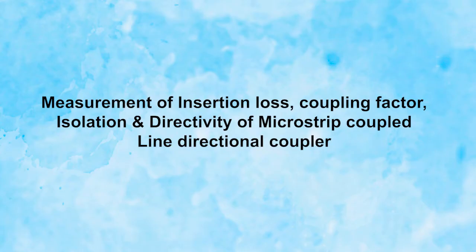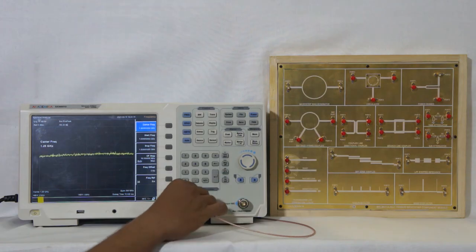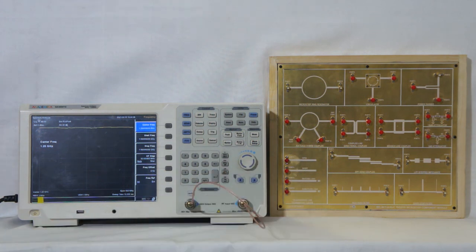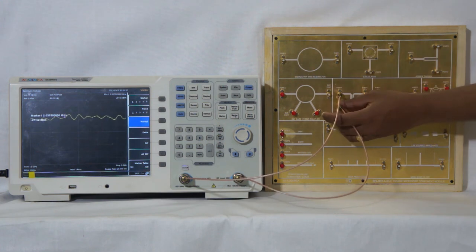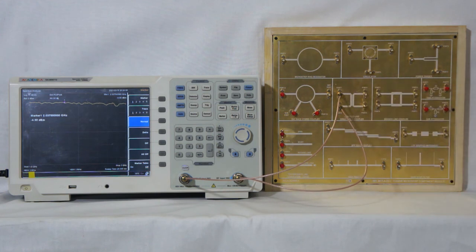Measurement of coupling factor, isolation, directivity of microstrip coupled line directional coupler. Set the tracking generator of the spectrum analyzer to 0 dBm and connect this to port 1 of the directional coupler. Connect port 2 of the directional coupler to the spectrum analyzer. Terminate port 3 and port 4 of the directional coupler with 50 ohm load.